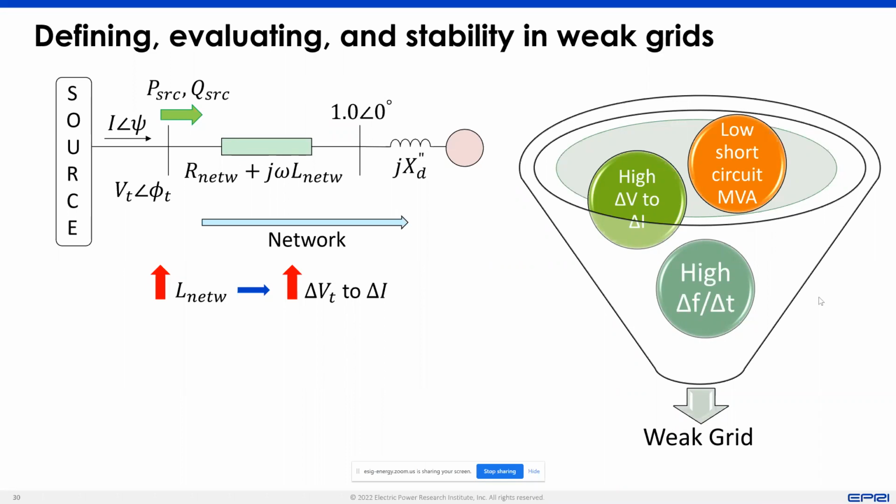And the kind of instability that might arise in that system can be very different from the kind of instability that can arise when you have a long transmission network, because the interactions are different. So the initiating factor may still be the same, that there is low short circuit current, but the type of interactions that can occur can be extremely different.